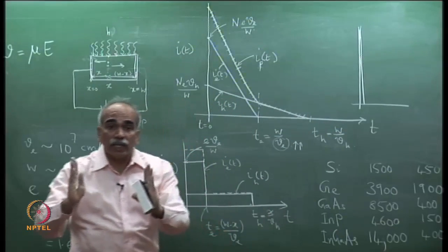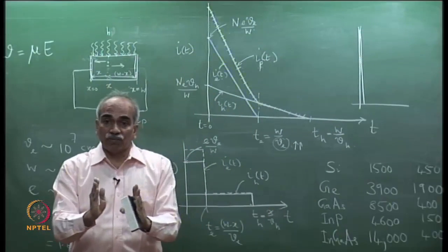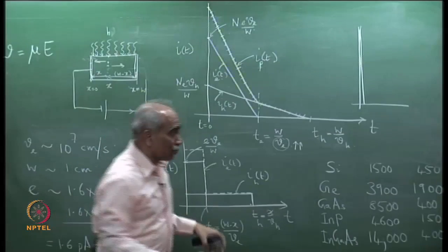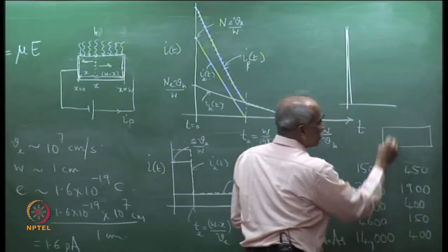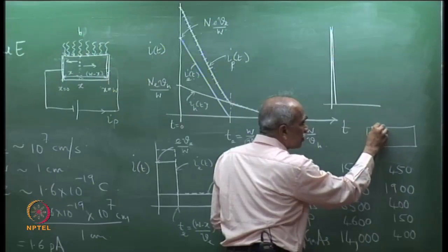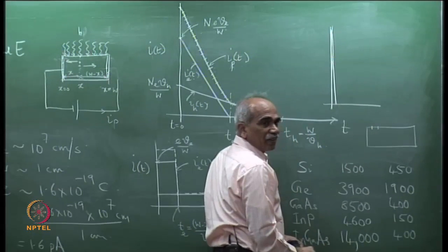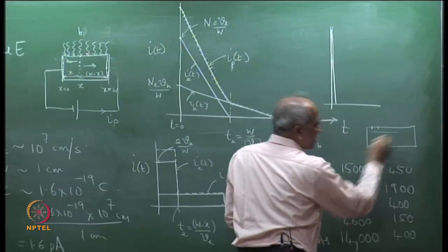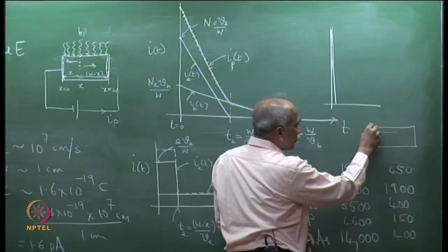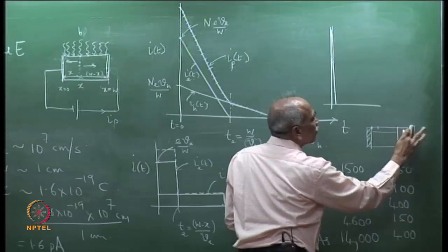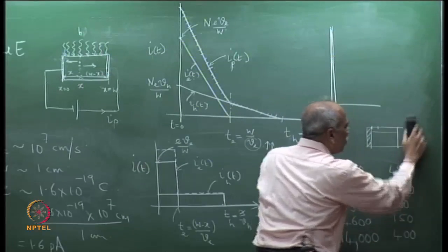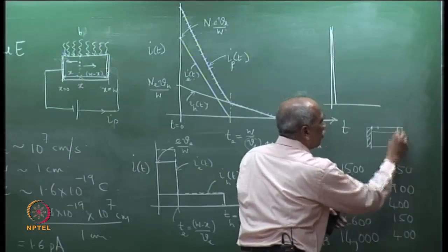So, if you can make T_e equal to T_h, how can we make that? It is possible that if this is the detector material, then you open a window somewhere here, then you see the electron will take a slightly longer time, whereas holes are very close to the window. Not that that is very good, but I want to avoid the pedestal.